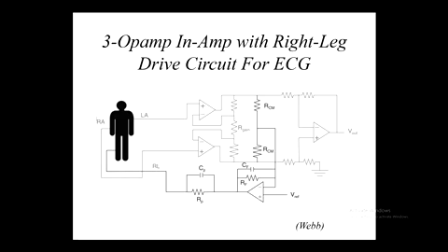Yeah. There's another aspect of electrodes that's an offset voltage. The electrodes themselves act like little batteries. With the silver chloride ones that you were using, it's about 0.3 volts. And that can get amplified by these amplifiers, because as well as being AC signal amplifiers, they will also amplify a DC.